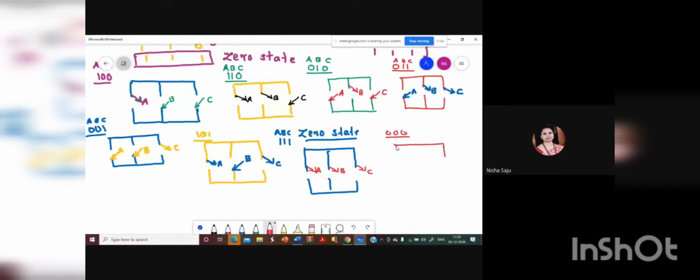So here, if you are having this much, then A part will be connected to pole A. This is your A, this is B, and this is C. This is your 0 state, shorted to the bottom right. So these are the inverter states corresponding to space vector modulation. You are having 6 active vectors and 2 zero vectors in the inverter switching state condition.